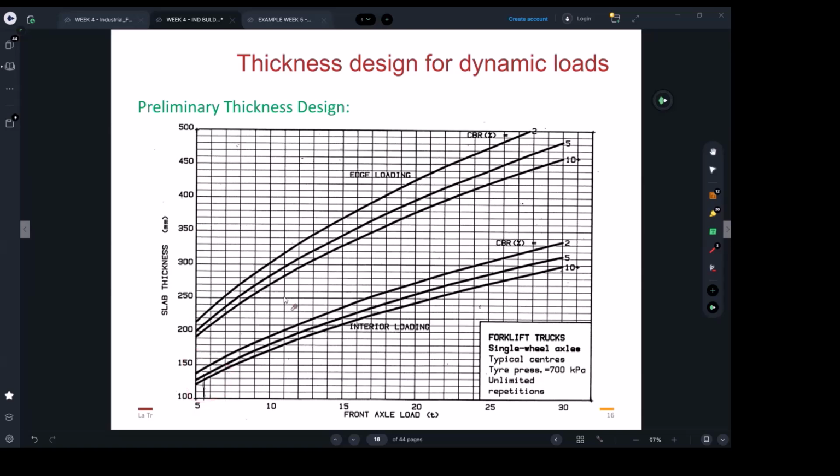So that's how you can use such a chart. And what does it mean for you? It's not only for design engineers, it's for construction engineers. Maybe during construction, you want to have some materials delivered or craned by a forklift or any other lifting equipment. Always make sure the loads will be limited by the thickness of the slab.